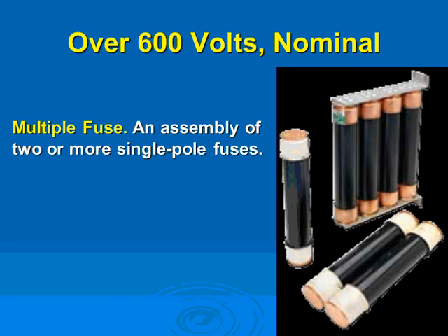They will all see it, and I believe so. Yeah, they will all see the short circuit, and the reason they parallel them is it gives you more amps. So you can have 1,000, 1,000, 1,000, 1,000, a 4,000 amp system. Each one of you will see 1,000 amp. If you have a short circuit right in here, they will all see the short circuit. They will trip, 1,000 amp fuse. So they are on the overload.